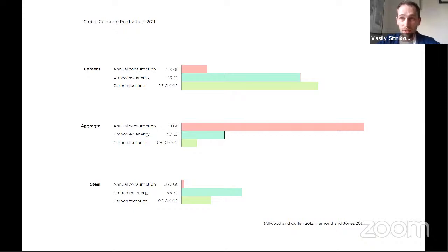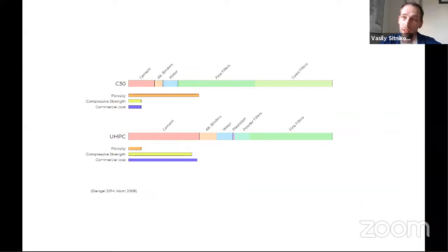So this was easy to understand very early on, maybe in the 70s, as soon as you just look at the chart of the components used in concrete. So there were taken and developed quite advanced strategies to reduce amount of cement in concrete to make it what is known today as green concrete. However, with less cement as a major binder in concrete, the properties of the material reduce. You will get a more porous material with less strength, practically, and these effects directly impact the durability of material. So by reducing the cement, one would make a green concrete, which actually would last less, and therefore compromise the life cycle performance.